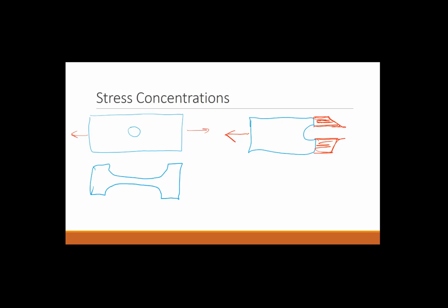Not like the dog bone you feed your dog, but what we call in structural engineering a dog bone, where we have a thicker section that then comes into a thinner section. And if we do that, then similarly, the stress is highest as you approach those regions where the cross-section is changing. As you approach those corners, you're going to get a higher stress.